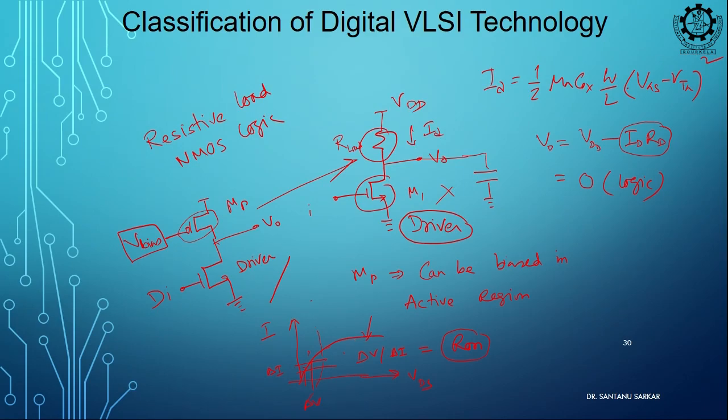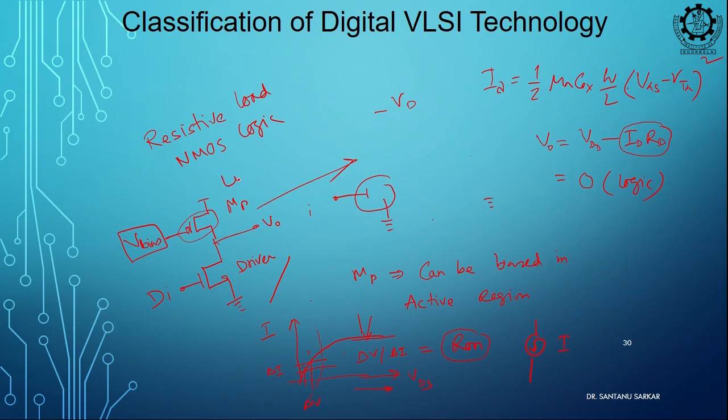So, if you want to implement a bigger resistance, we can think of this. So, current source load. Okay. In this case your voltage is changing, but current is fixed now. So, if I model this transistor in saturation mode, this can behave like a fixed current source of value I. You see the same thing, just how the circuit is varying, the definition is getting varied. This MP is in linear mode, R on.